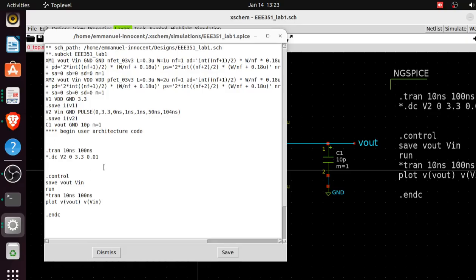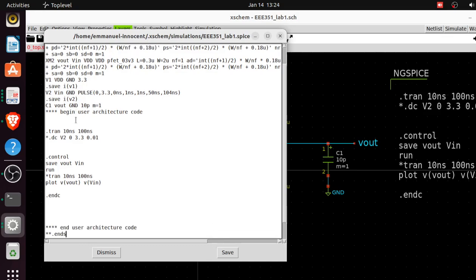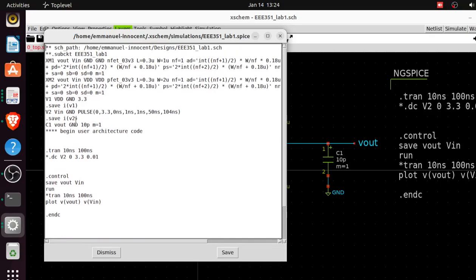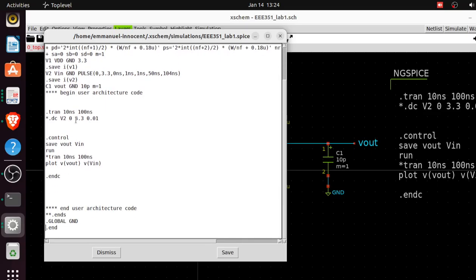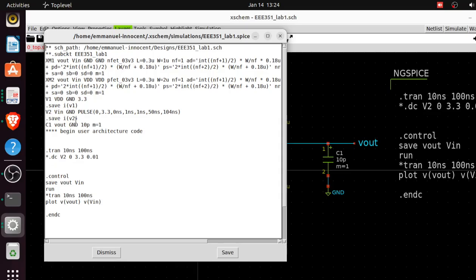spice directive here. When we click the netlist, it gives us the full netlist, so we can see everything. The advantage of this is when you get to understand spice language, you'll be able to go through it yourself and confirm that everything works well. Sometimes the simulator, if there's any error with the graphical schematics you've made, won't even show anything. It will tell you that there's an error, then that way you know. So that's the advantage of generating it.